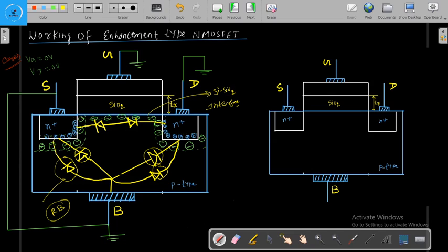So here we have seen two things. The first one: when Vg is 0 and Vd is 0 volts, this region of operation of the MOSFET is called the depletion region. And the second thing is we keep the body terminal for the N MOSFET at the lowest potential, because we don't want these diodes to be in forward bias. Now we are going to see case number 2. Let's see this.